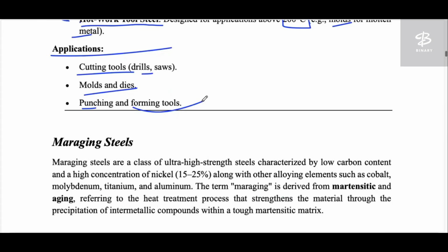In that example you are actually using blanking, not punching, because whatever came out of the punching, you removed and treated as waste material, not used as the final product. You just leave it. So this is the best example of blanking.